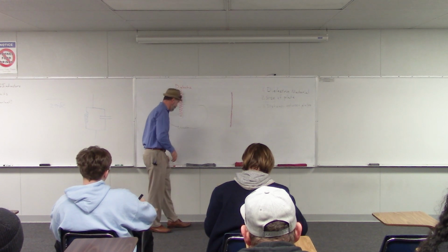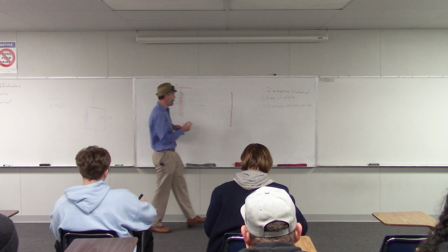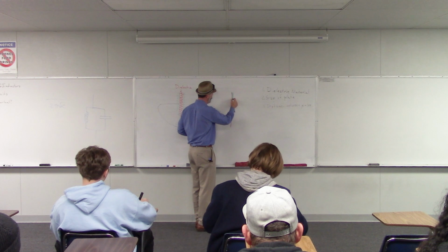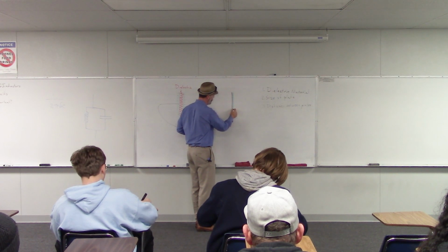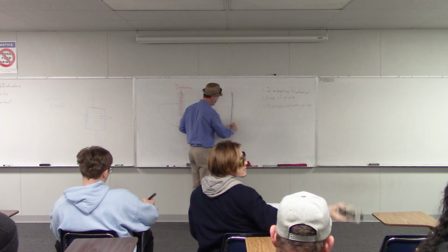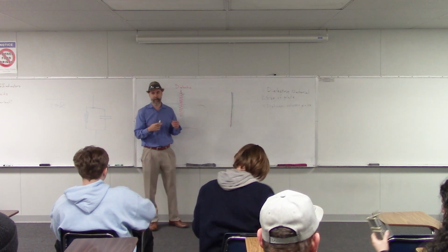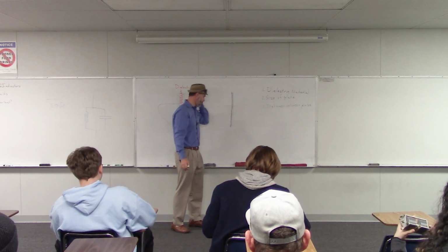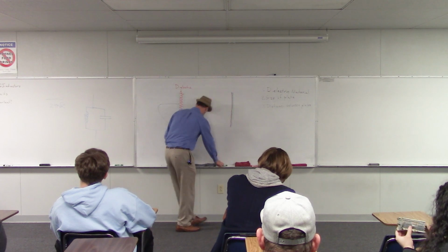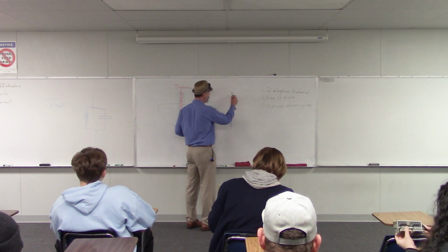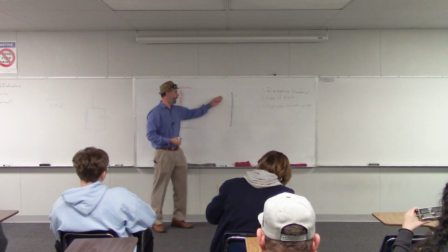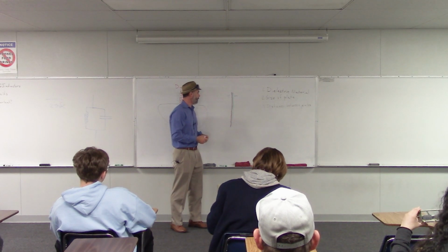And then the other conducting material is a liquid that is impregnated into a cardboard material. So this is the sandwich that they make, and then they roll that up, and that's the electrolytic capacitor. My understanding is that if you put a positive voltage here and a negative voltage over there, then everything works fine and you get this capacitance.